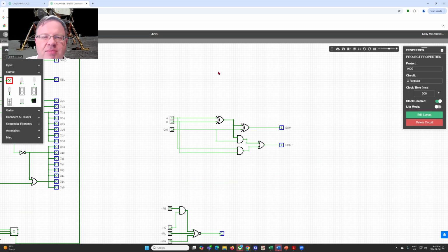So that means you've got to potentially propagate that carry bit across, in the case of the Apollo guidance computer, 16 bits, and in the case of a more modern computer, 32 or 64 bits. Now, this can cause a delay because it has to propagate through all of those different bits in order to produce the final sum, where the high order bit is the last to settle.